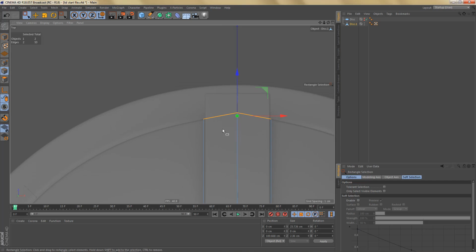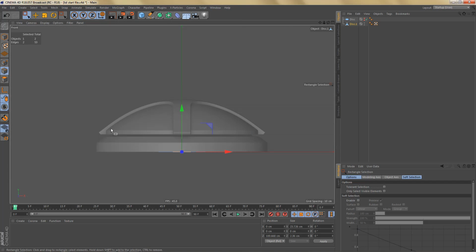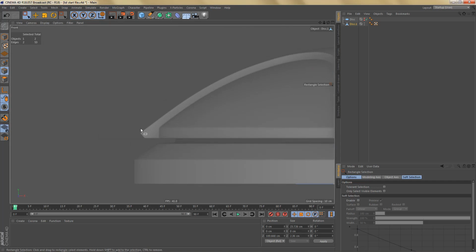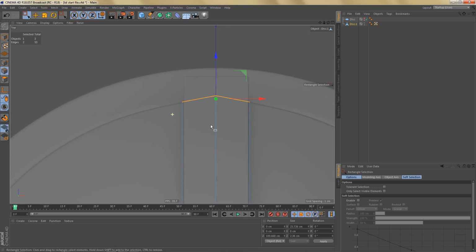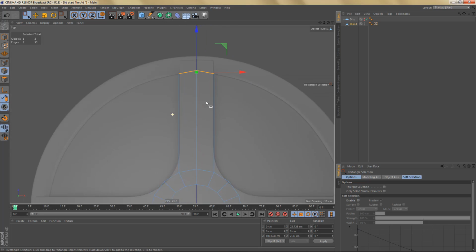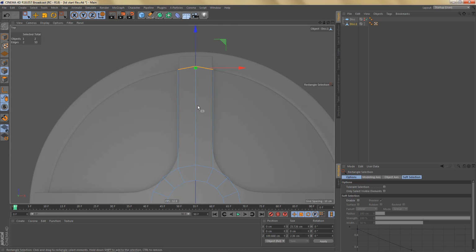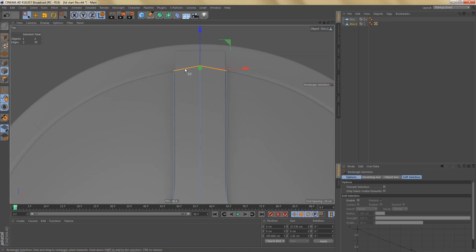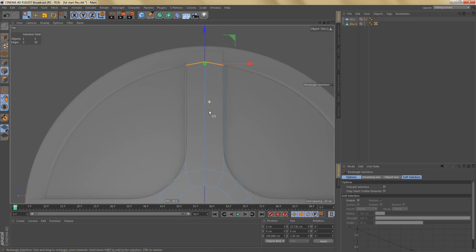And you can see this extrusion here is a little bit longer, and it creates this shape here and goes beyond that circular shape of that disk object. But for now, we're going to keep it like this because later we will need to deform the object using shrink wrap and a sphere, and we're going to get less distortion if we add these extensions later. So for now, I'm going to keep it like this.